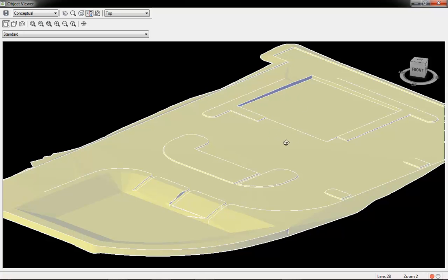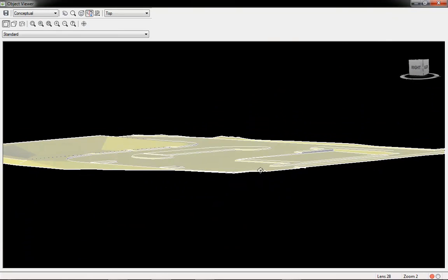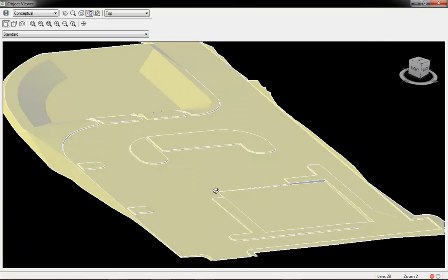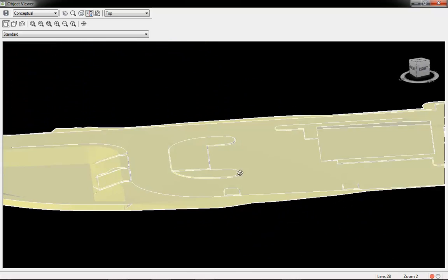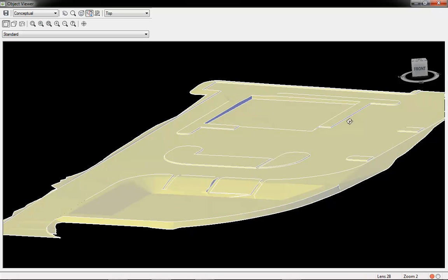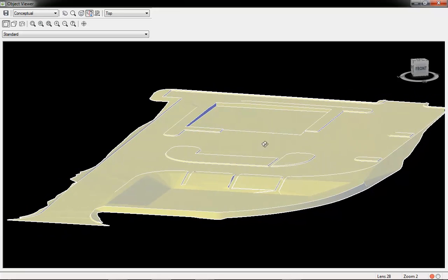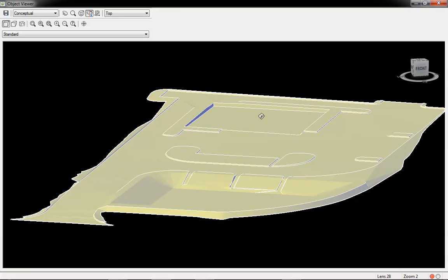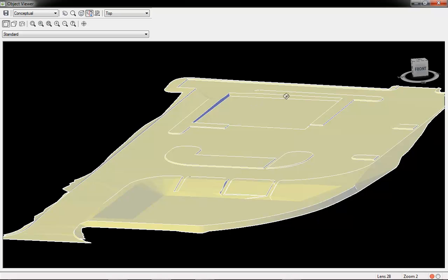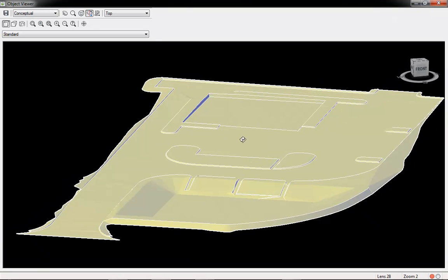And then here's a building pad. So you can see how the pad is flush right here where you're walking in from the parking lot. Walk right into the building pad, and the building pad is flat. Now since the proposed grade goes upwards in elevation toward the north end, the building pad still stays flat. You can't have the building pad go up. So the building pad elevation is 734.3, so it's cutting into the exterior elevations around the outside. Then you got your islands.